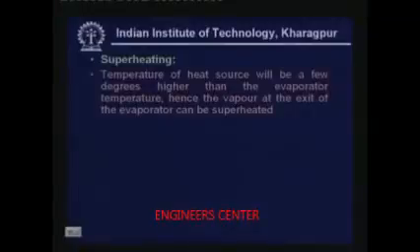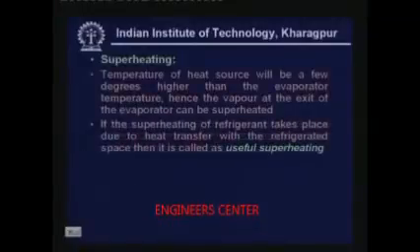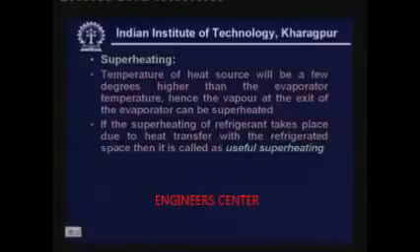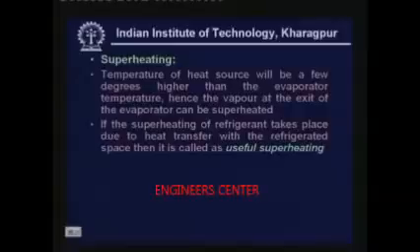What do you mean by useful superheating? If the superheating of the refrigerant takes place due to heat transfer with the refrigerated space, then it is called useful superheating. That means if this heat transfer is taking place inside the freezer compartment, then it is useful because the cooling effect is ultimately given to the products. So you call it useful superheating.